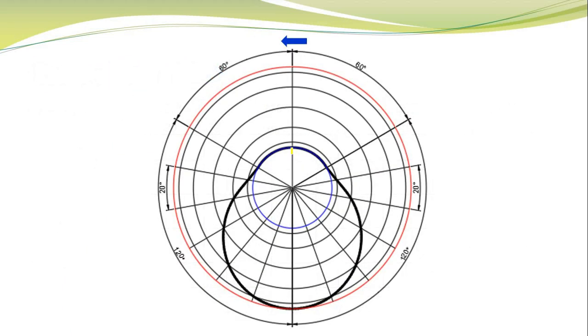So what I can do is, from this point over here, measure a distance of 40 mm, done. And then from this center, extend your compass over here and draw a circle. So this becomes your maximum stroke circle.